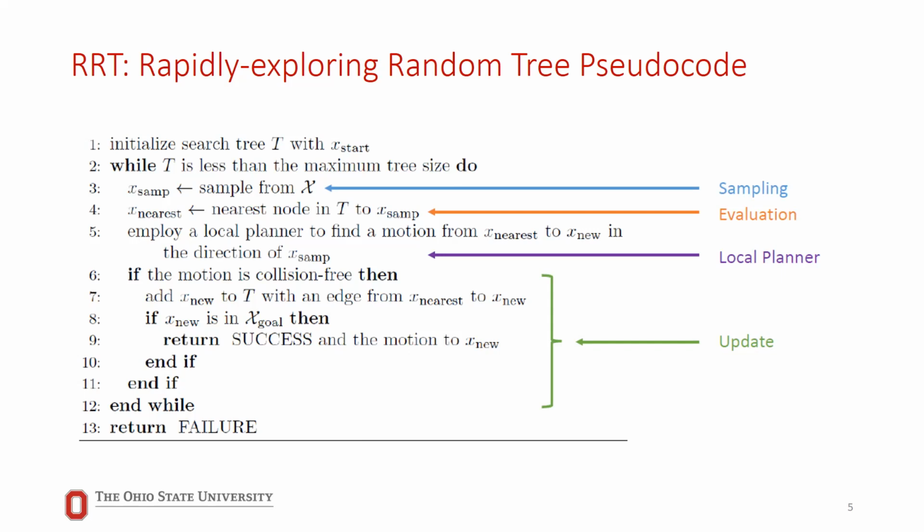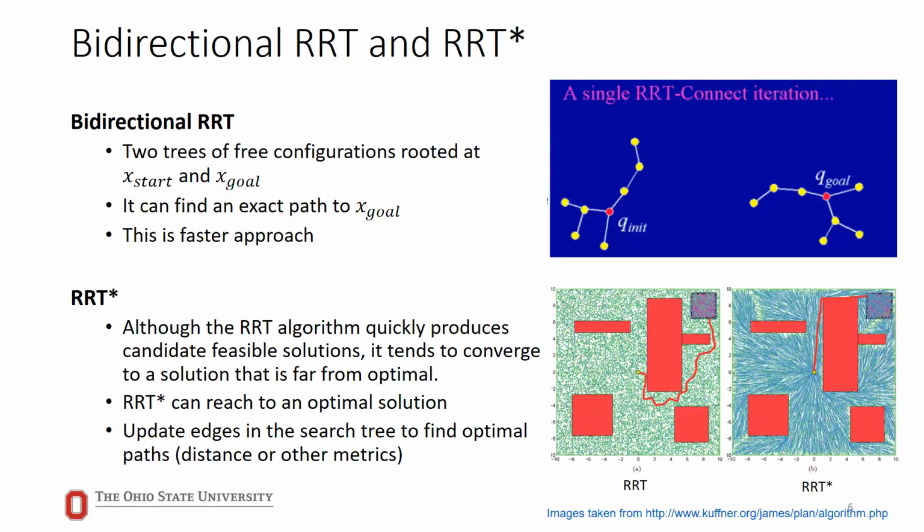So that's different. Terminology is important when you say local planner. We are in our local area, the nodes around it. Then there will be an update. So if it is collision free, yes or no, if yes, move to the next point, update all the nodes, and do it all over again until this tree grows.